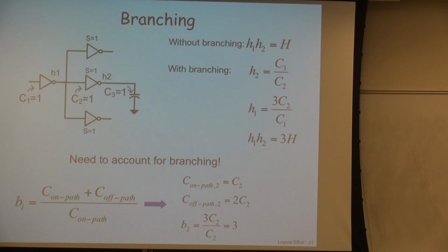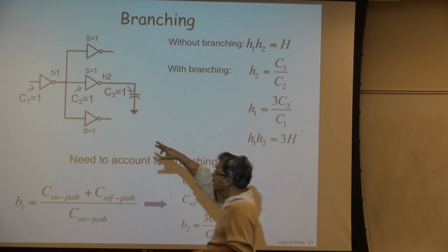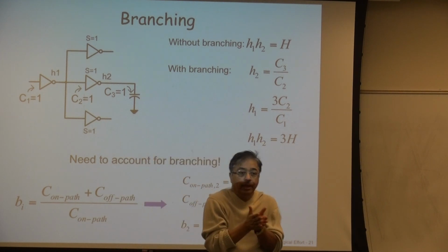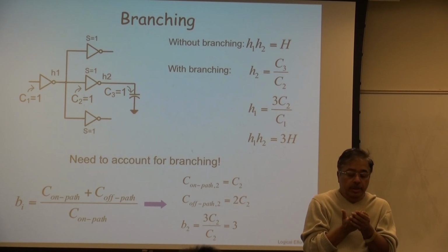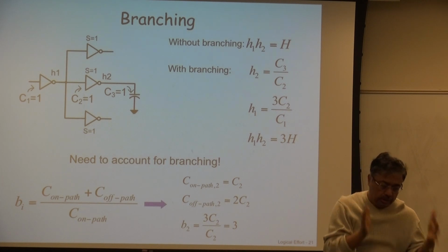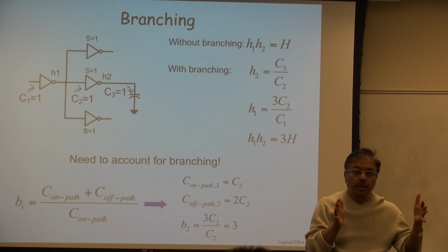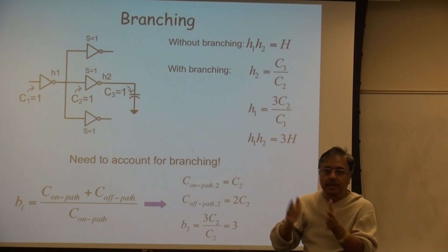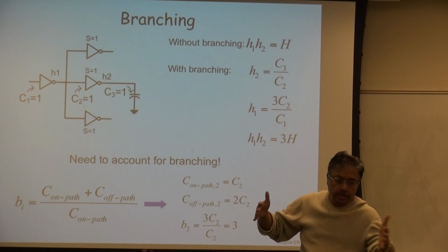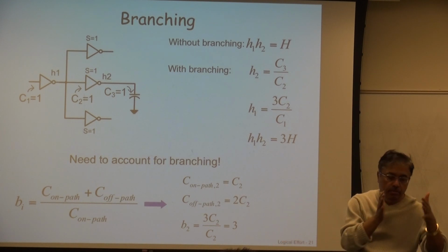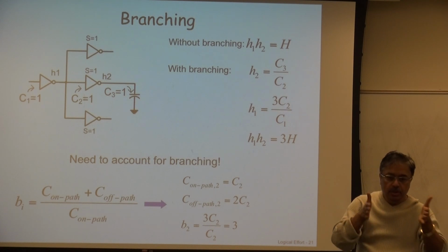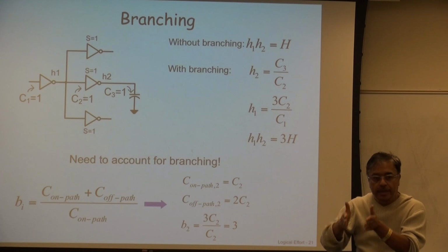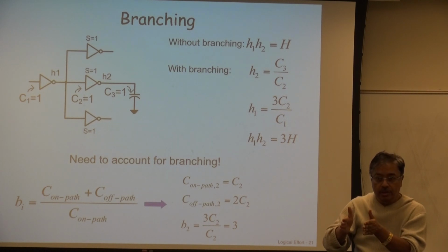And we are trying to optimize the delay of the critical path because that's going to be the, now all this branching thing may be smaller delay, so we don't really care if the transistor is optimized or not, actually, right? Because in a pipeline adder, all the stages have to compute simultaneously, then only you can move on to the next, you can bring in the next data set, right? I mean, if you are loading the pipeline with different data sets, whichever stage has got the largest delay, that will decide the clock frequency, correct?